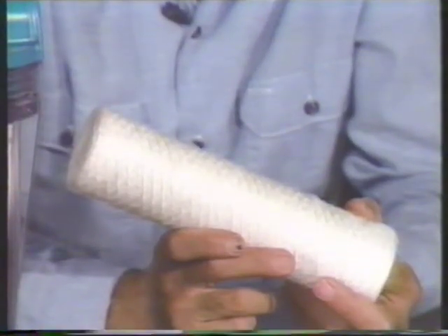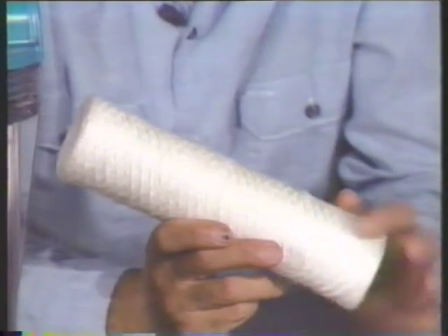Different types of filter media are used in filter tubes, depending on the fluid being filtered and the size of the solids being removed. The filter medium is the material that does the actual separation of mixtures. For example, the filter medium from this tube is a man-made material wound around a central core. Other filter media used in cartridge filters include special papers and porous plastic.